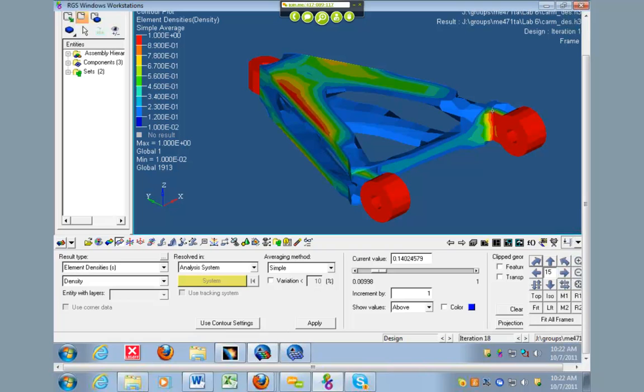Yeah. As you use this tool more often, you will use a lot more of the different types of optimizations, and you can actually get a mathematical value that will do what you need. But for right now, just eyeball what the ISO value is. So 0.15 is a pretty reasonable one. You've still got material basically wherever you need it.